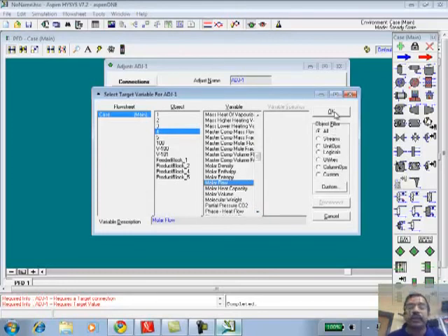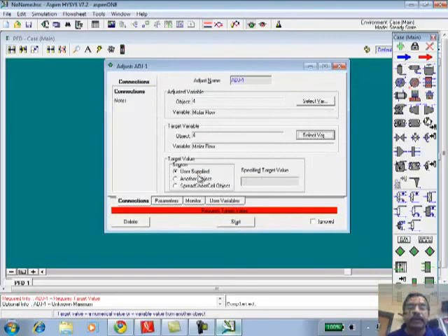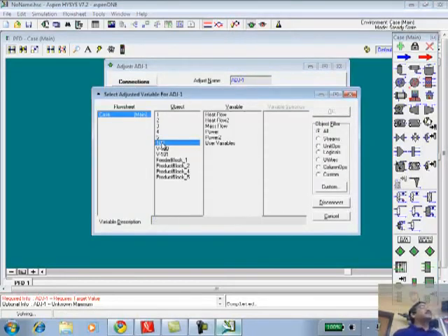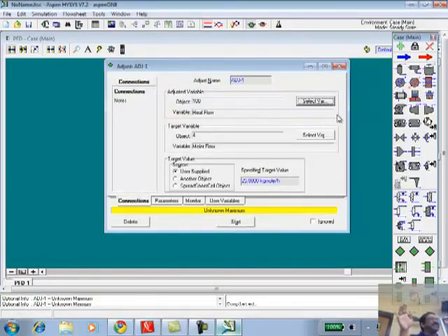You adjust the load on the target values. User specified. Yeah, target value here. So we want the target. Thank you, that's very observant. Okay, target value to be 25 kilogram mole per hour, and the adjusted variable is wrong. What we specified, so what should that be? It should actually be stream 100, because that is the heat stream, and we want the heat flow. I think so. I don't know what heat flow 2 is. I told you I'm flying blind because we are exploring something new.